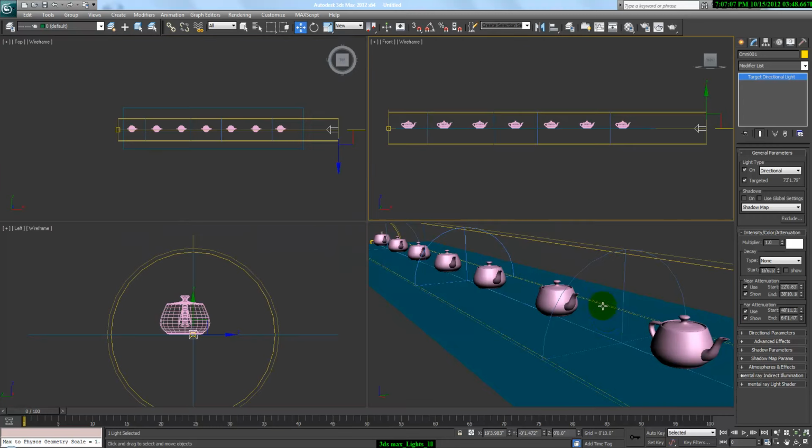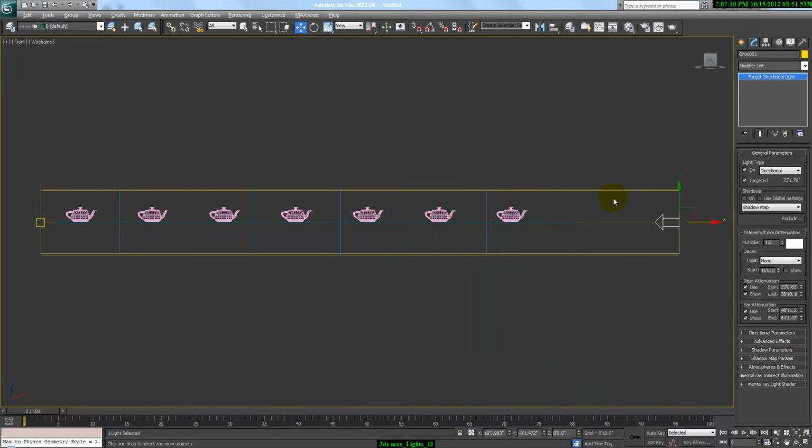Okay. Now what happens is, in near and far, our light decays, it decays here with a particular rate of whatever distance we are giving here. But here manually we can give it where to start and where to end. Near attenuation means that when it says start, the light here, the multiplier, whatever it might be, 1.5, whatever, let it be 1, 100% of the light. So at this point, the light will be 0 till the start. From start, it will start rising from 0% to 1, and at the end it will become 100% of whatever is available.